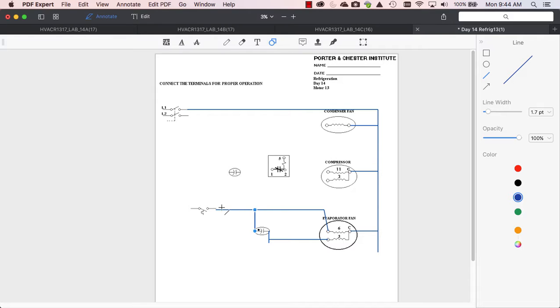Now when we have a start cap, this motor up here, the compressor, is a CSCR. I'm going to go ahead and we have a potential relay here. 1, 2, and 5 is the dead giveaway on pin numbers. We'll bring power in there. This motor, the one with the 11 ohm winding, is your start winding because remember, start is always more than run. So we'll bring that in there. Pin 2 goes to start winding.